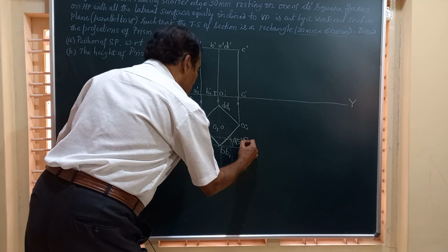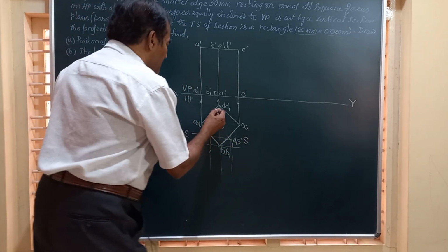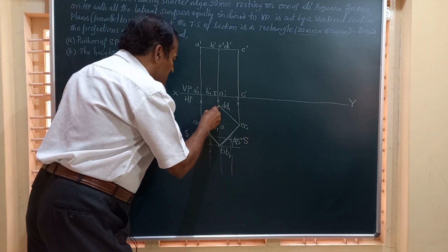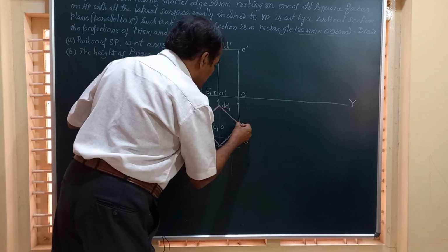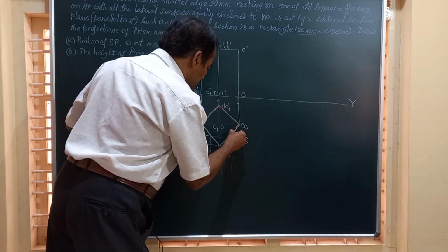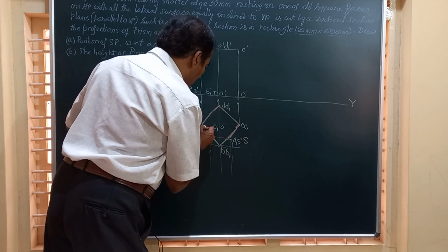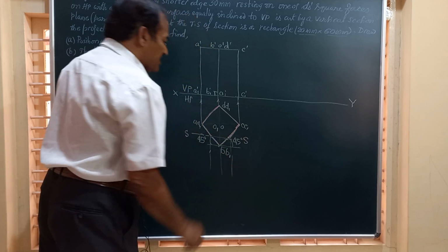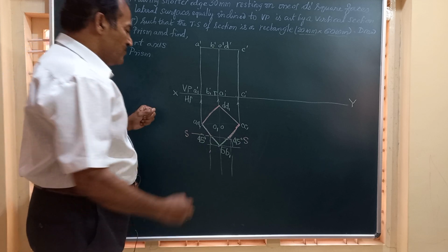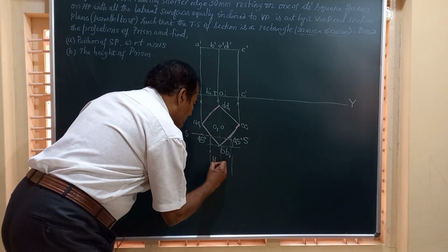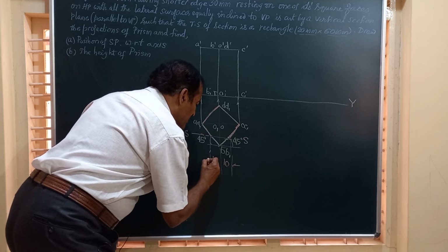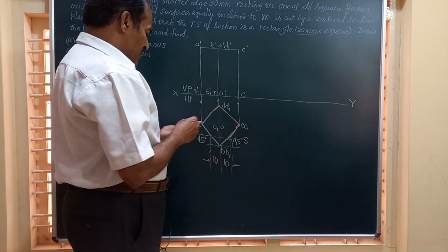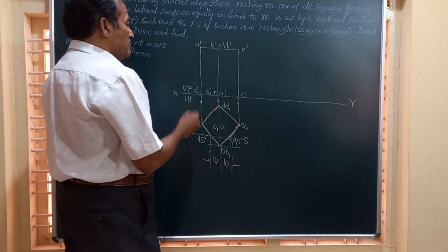So after this is being cut, the portion that is left over is the portion I am showing now. This is the part of the prism that is left over after this is being cut. This bottom portion is removed. Friends, this has got a dimension of 10 millimeter. This also has a dimension of 10 millimeter, because the total width should become 20 millimeter.